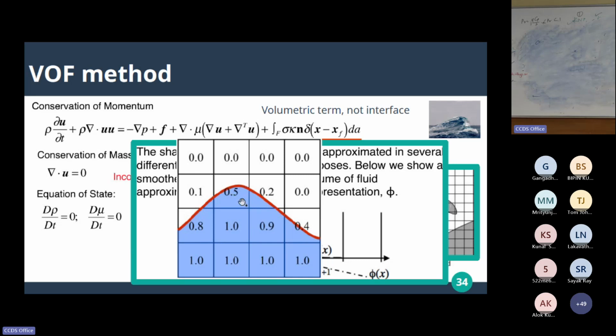Maybe put some diagonal line, fill the bottom of the diagonal line with 0.5, leave the top, or maybe some other arrangement. So all these VOF techniques and improvisations are about how carefully I can put that color and whether it really makes sense. If I am in a position to do that, we are successful. Otherwise, whatever solver you pick is going to fail.